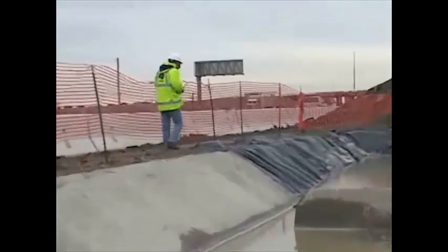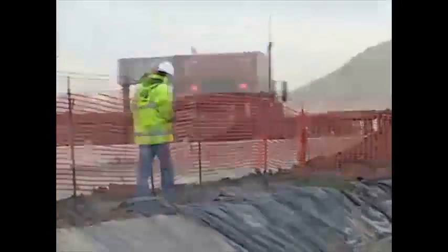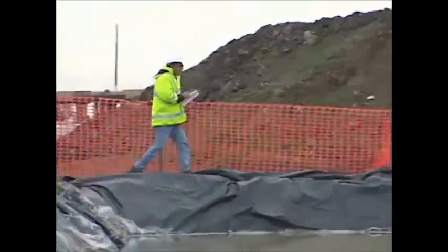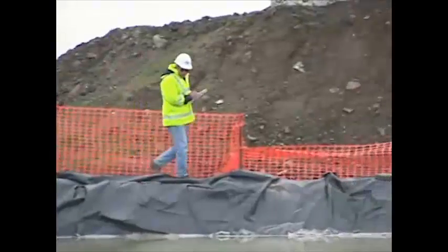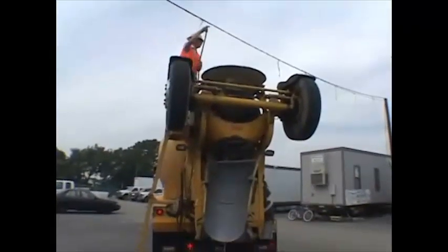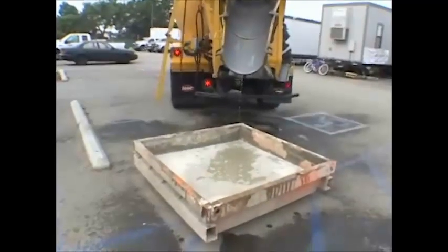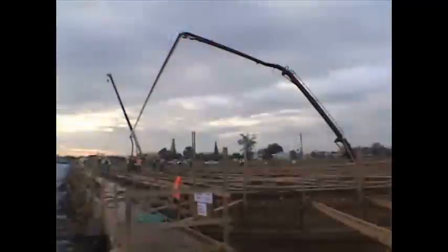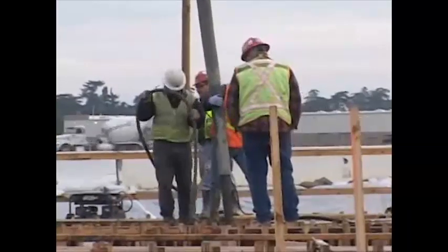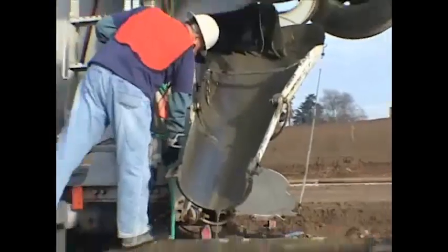In the event of concrete washout overflows, discontinue using the washout and construct a new facility to contain anticipated washout operation wastes. Provide temporary containment to collect wastes that are generated when pumps and transfer hoses are cleaned out away from the washout. By following these procedures, you will do your part to minimize or eliminate the release of concrete waste materials into the storm drain system or watercourses.